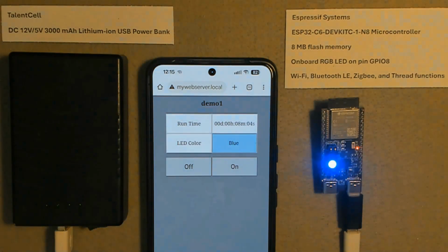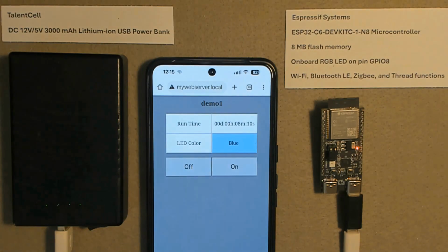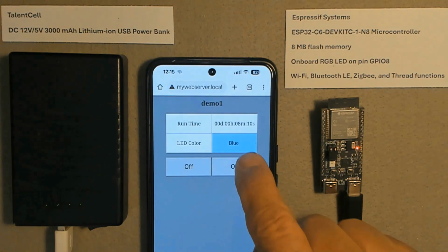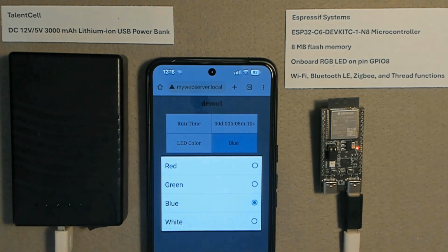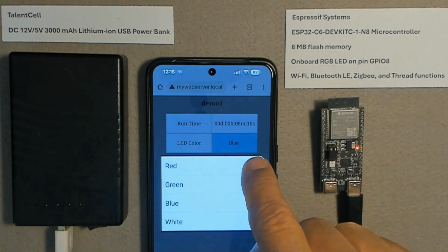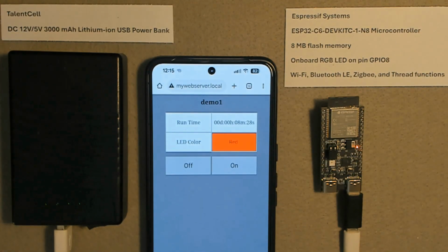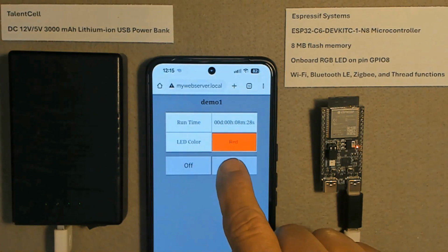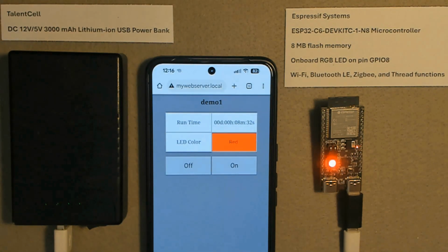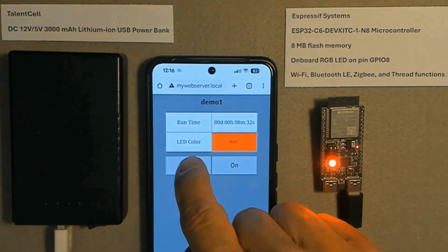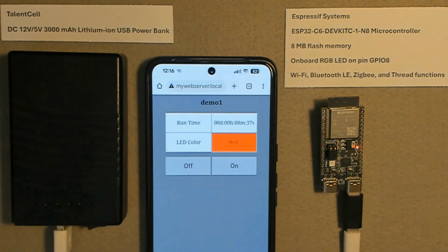In this demonstration, the web page displayed shows how long the ESP32 microcontroller has been running since it was powered on, as well as web page controls and buttons, so the user can remotely change the ESP32's onboard LED control and turn it on or off. The code provided can be easily adapted for other projects to display different ESP32 attached sensor information and remotely control ESP32 attached relays, dimmers, motors, etc. Following this demonstration, I will show and explain the program source code that can be downloaded for this project.